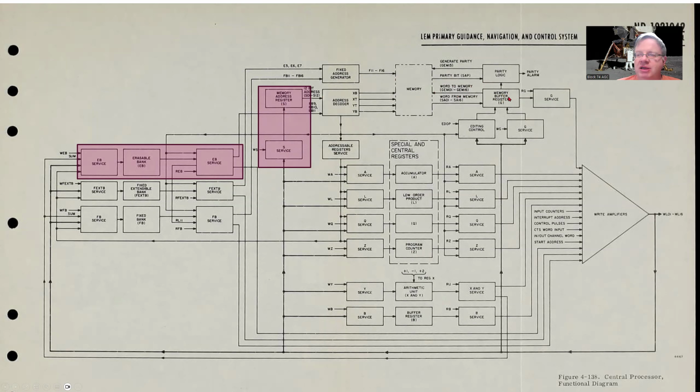We'll build the parity circuitry just to keep historical authenticity, even though with modern memory we probably don't need it, and we're not going to be flying it through the radiation belts or out to the moon, so we won't have to worry about that radiation environment, which can cause some issues with memory. Anyway, back to the S register.